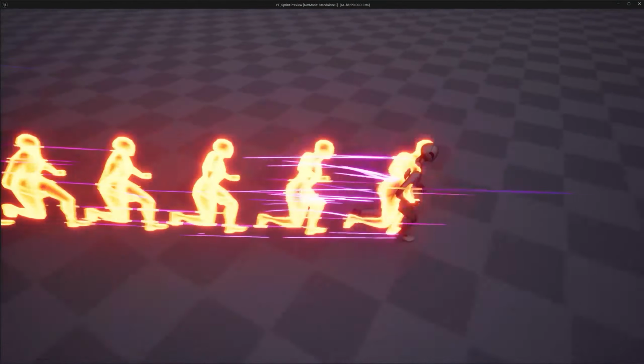Now you can see that it is very jarring because it is just popping up like that. So we can fade this a bit. So in order to do that, we can go back, and here we can go to particle update and type in scale color. Then for the alpha, here we can click this and type in curve, and then select this one. So it will start at 0, then go to 1, then fade out like this. So now if I just press play, it will look like this.